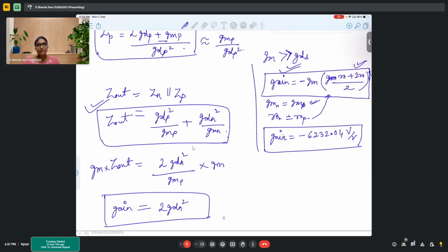In that case, when they're different, we have to take basically the small signal model of all the transistors and then solve. That is the best way. So you won't make any mistakes and you'll reach the correct results. But for the problem's sake, that never happens. It is always the case because your currents remain constant. So generally, your GMN and GMP also remain constant, and so you always boil down to this simplified formula only.